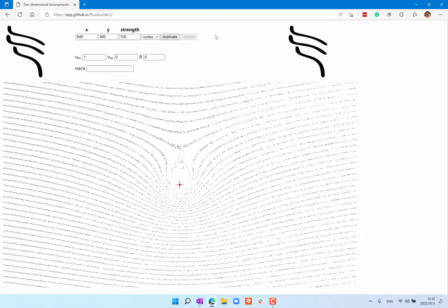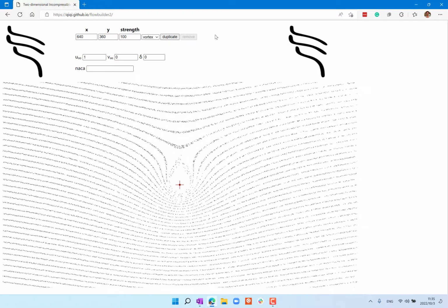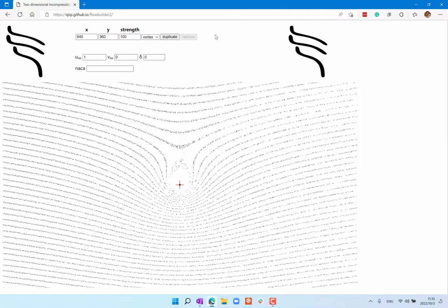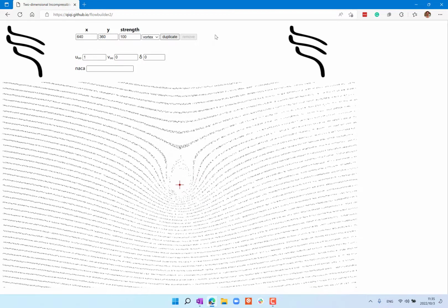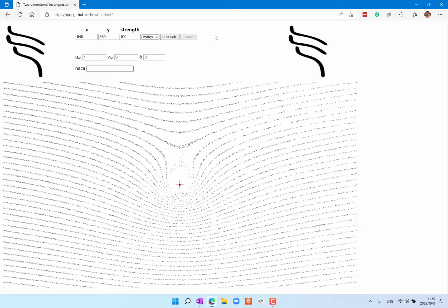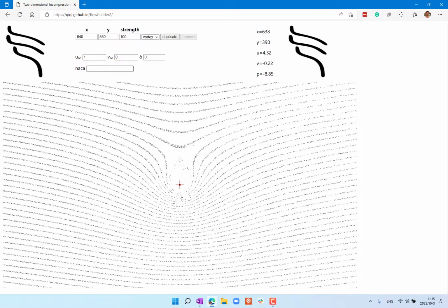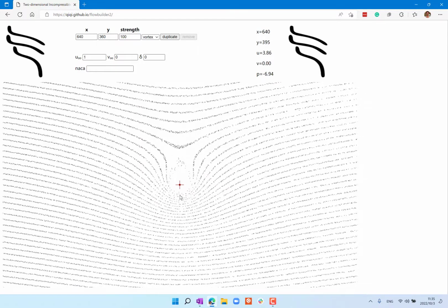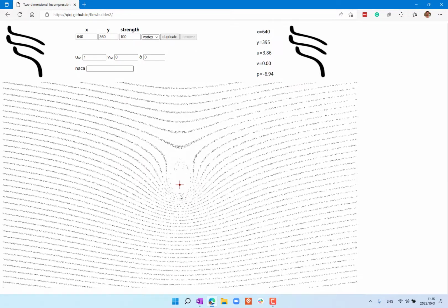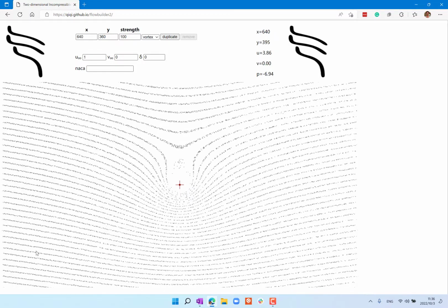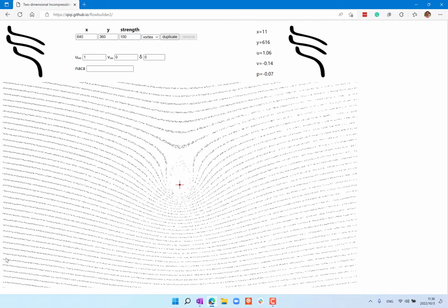And in this case, we see this airfoil gets a huge negative lift, right? So the lift is going to be towards this direction. Why? The pressure here is high. The pressure here is very low, just Bernoulli's. The streamlines are so narrow over here that the flow velocity must be very high and the pressure must be very low. And you can move your mouse to here and see, right? The pressure here is like minus 6.94. And by the way, the units are the following. The pressure at free stream is set to be 0. So if you move far away, you get pretty much 0.